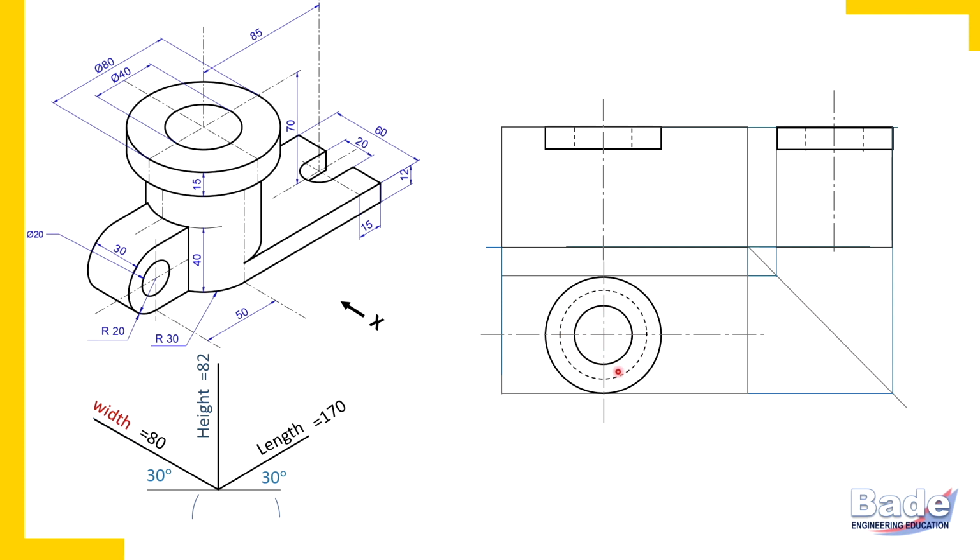Watch this dotted circle, what it is. So of course the cylinder which is under this disk, and it is hidden in the top view, and that is why it is a dotted circle. How are you going to draw views of this cylinder? As usual, in top view circle, remaining 2 views rectangle. Let's do that. So here the circle in the top view, dotted, we have already drawn. Now I have drawn end projectors, and here the cylinder is complete. And now draw end projectors from top view to side view, and you will get the corresponding rectangle in the side view.